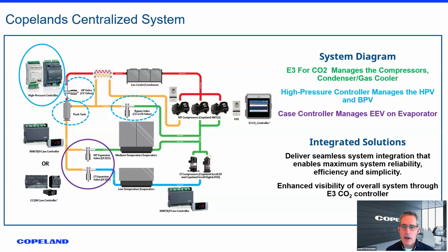Okay. So now we want to drill down on exactly what you're interested in here, which is the high pressure controller and what its function does in a CO2 system, because we didn't have those in HFC systems. This is unique to CO2, right? Even though you look at the high pressure valve that's sitting here, that is connected to it, well, that's kind of the position that a holdback valve used to be on an HFC system. Sometimes it's used as a holdback valve here, and sometimes, as we'll get into, it's used as just a high pressure expansion valve.